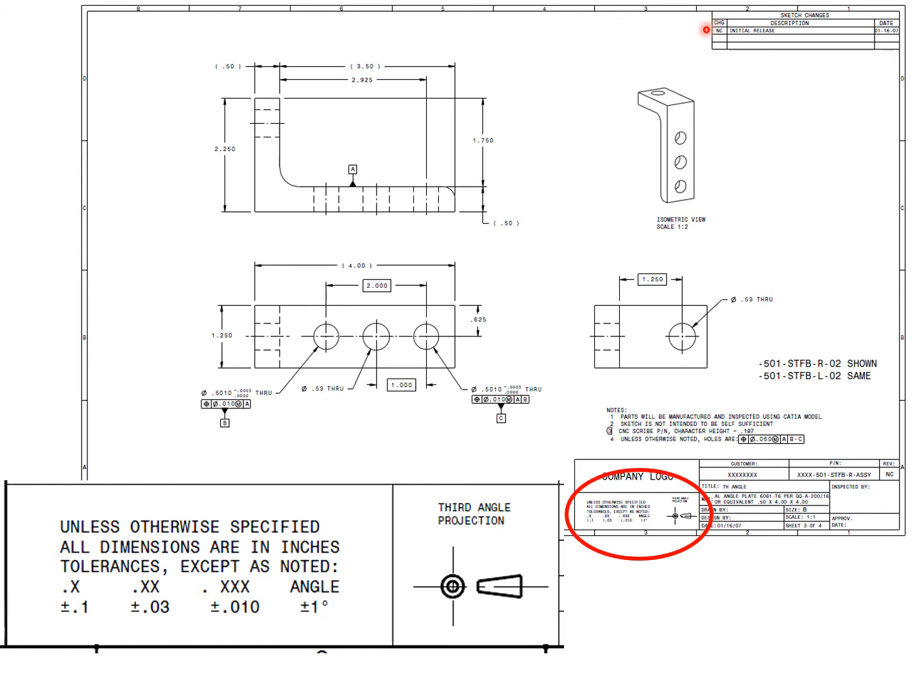Once we make a change, we would now use the alphabet and start with the letter A and a brief description of what you changed. Diameter 0.59, change to 0.65 diameter. Look at zone 6B. So this is letter B, this is number 6. You tell them at zone B6, look in that area, look for that dimension. This dimension now has been increased, or the diameter has been increased. And then at the end you have the date of the change and typically the initials.